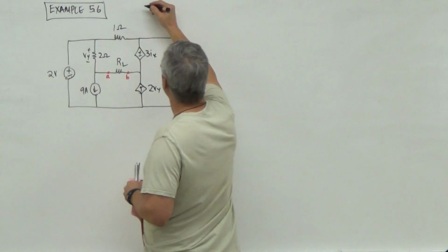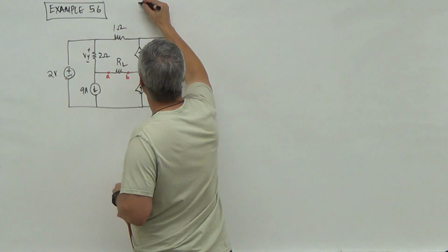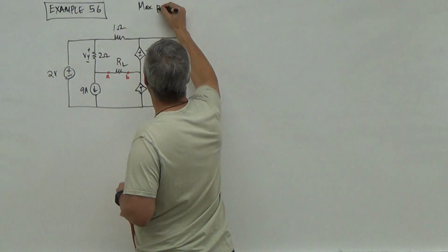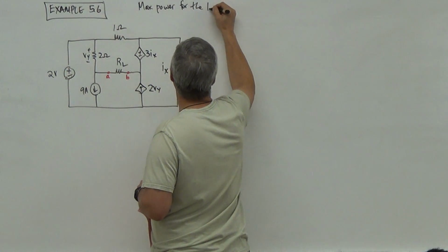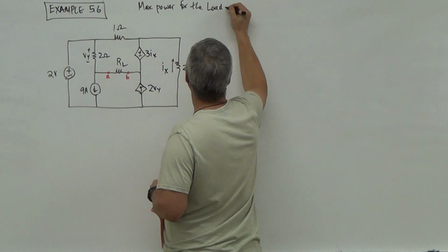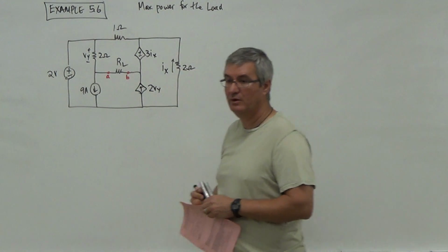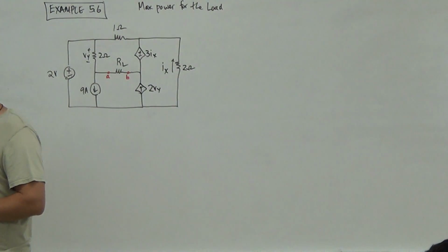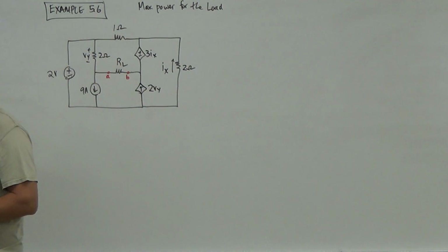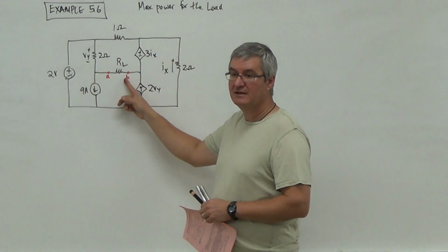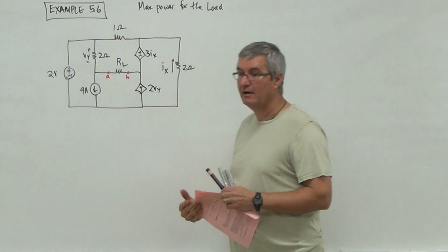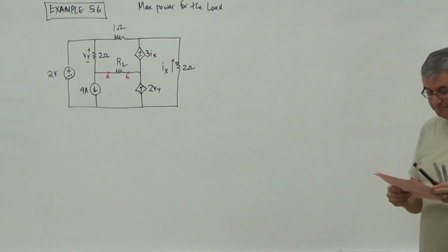So they want max power for the load. How do I get that maximum power? Well, we already know that the load better be the Thevenin resistance. So I have to go find that Thevenin resistance and then calculate that. Let me give you some time to do that.